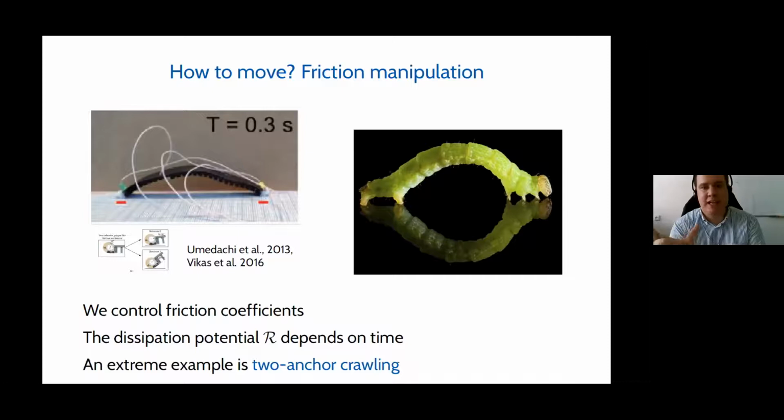The inchworm again has only one degree of freedom in the shape, so it's just contracting and expanding, but it can control the friction coefficient. So it can grip on one end while releasing the other end. For instance, if you grip the back end, release the forward end and start expanding, the forward end would move forward, and then you can do the opposite to carry forward also the back part.